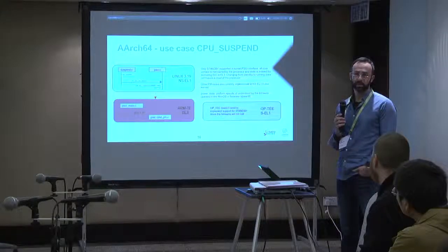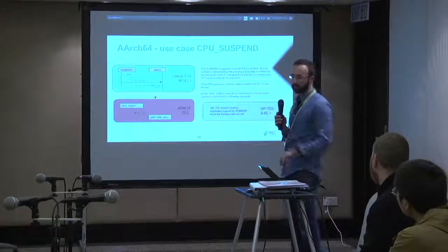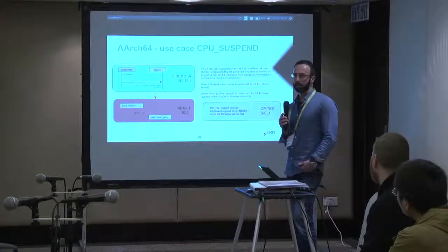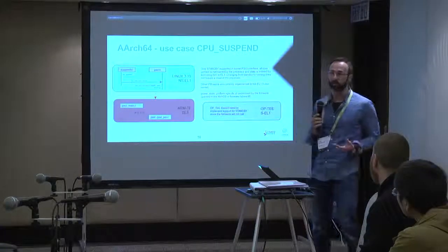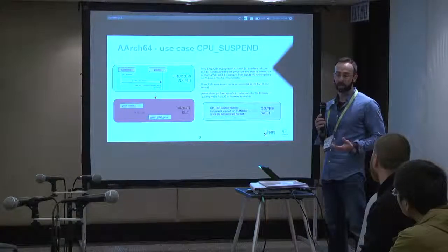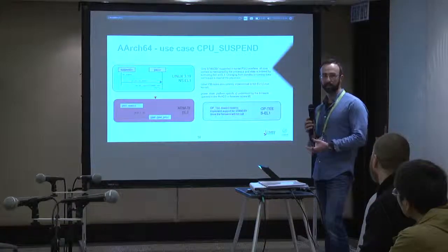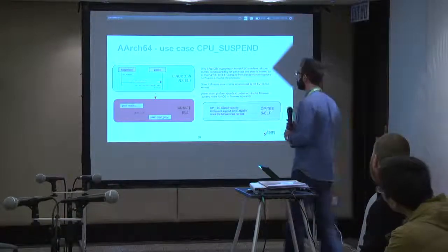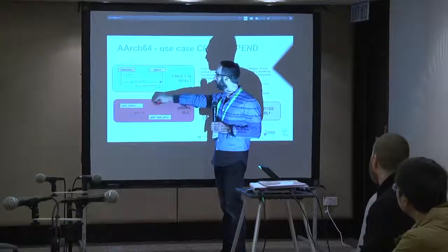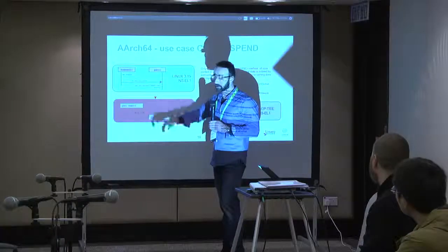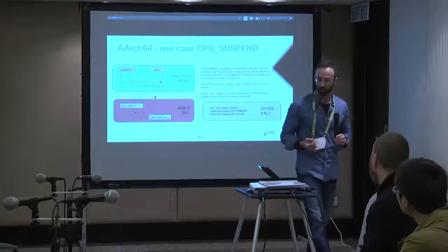Basically, those fields are in firmware tables, in the device tree. So if your platform has a number of special configurations that will need to be handled as part of the platform, you will provide those in the device tree, and when the suspend state or the standby state is requested, in the request field, you will specify which state really you want to go into.